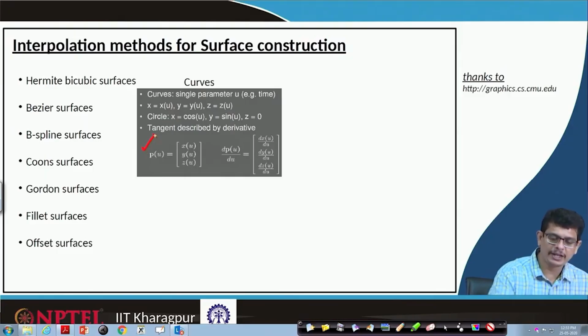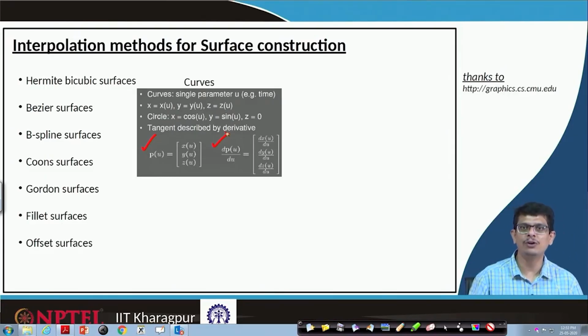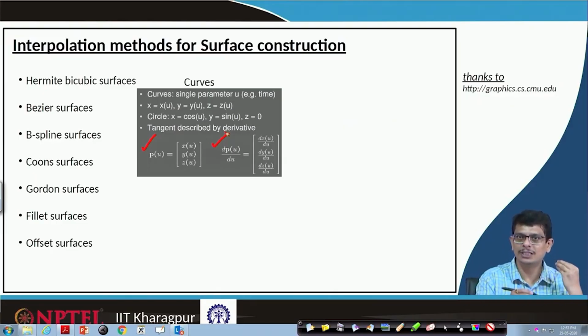So, we require the point information and also the tangent information. If we have that, we will be in a position to draw a smooth curve. It is like on drawing sheets earlier, when we tried to draw smooth freehand curves. That is because our vision says that from this point you go in that direction, but to the computer you have to teach it to construct a tangent, go to the next point by integration, maybe Euler integration, join those and construct a curve.